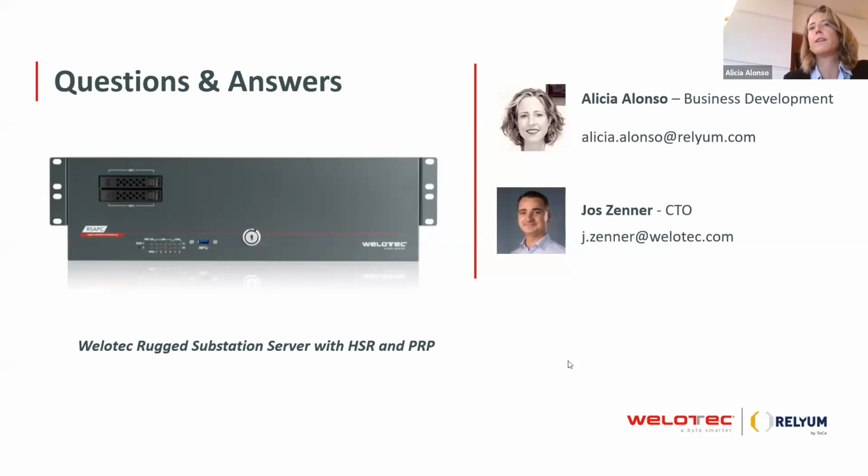If you have only one switch and you have any problem in that switch, you will lose both LAN A and LAN B with this configuration. So all PRP networks rely on 2 completely separated physical devices, 2 completely separated networks, and the same topology for LAN A and LAN B.